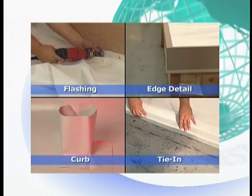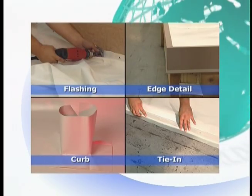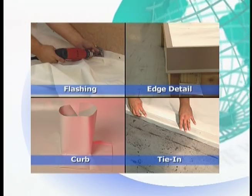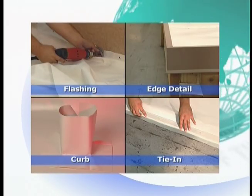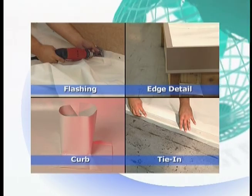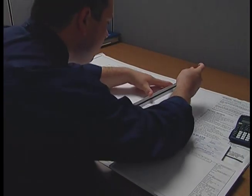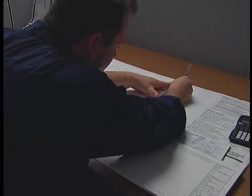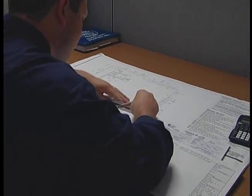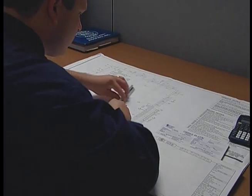Finally, you must have all required measurements for flashings and edge details, curbs and protrusions, such as pipes and stacks, and tie-ins. These are crucial to ensure that you order the correct material to complete your job. This DVD provides further directions for flashings, edge details, curbs, protrusions, and tie-ins. You can select these topics from the DVD menus. After you've gathered and recorded all the required information, you're ready to start organizing your order. You'll soon see that your efforts during your survey will pay off. Because of your advanced planning efforts, your installation crew will be installing a Duro-Last system quickly and effectively.